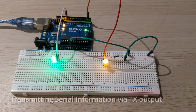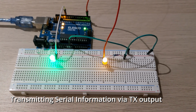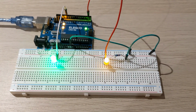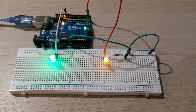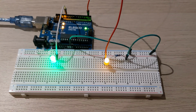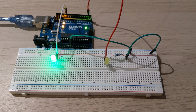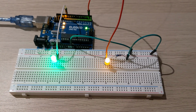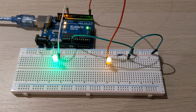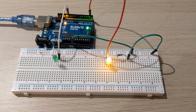A serial print not only sends structured information to the host through USB, but also through the Arduino's TX output. The setup is very simple. It writes very long strings and individual bytes to the serial interface, using a very low baud rate, so that their individual bit signals can be roughly seen on the right yellow LED that is attached to the TX output. The left green LED stays enabled before we start sending commands to the serial interface and is disabled once the writing phase is completed. Notice that even after all writes are committed, there are still bits flowing through the TX output. This goes on until the Arduino's internal serial communication buffer is completely flushed.